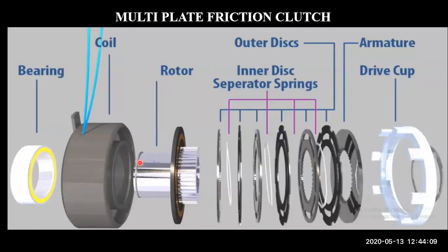So in multi-plate, you just have multiple plates. As I showed before, you have multiple plates here, which are connected in between the shaft. This is for better control and faster engine operation. When you engage all these, you need to give some artificial cooling, as the heat generation also drastically increases with more plates. So you have this entire casing which is cooled. You see these pipes go in, which are used for cooling purposes. You have liquid going in and coming out.